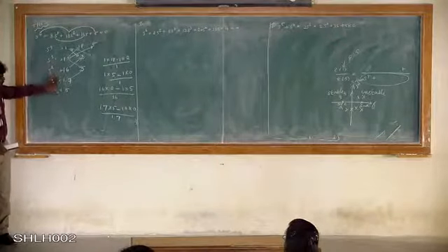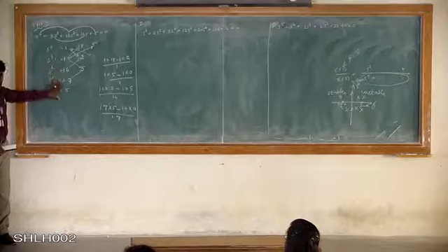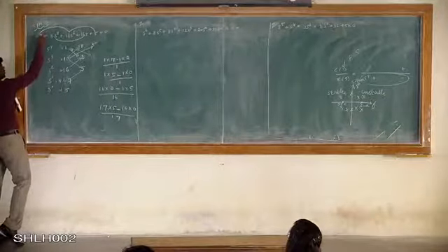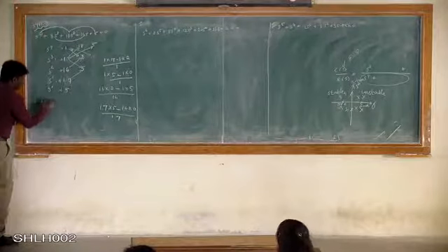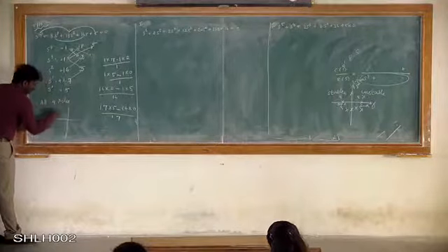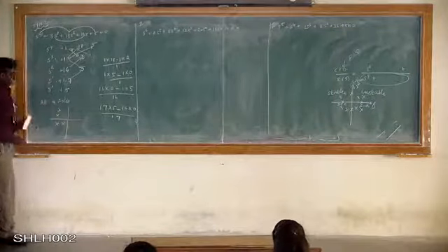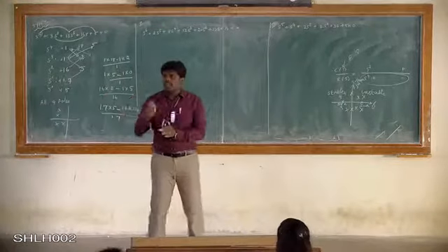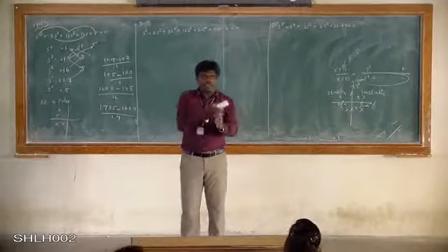Now all these values are positive, so that means it is a fourth order system. All the 4 poles are lying on the left half of the S-plane. Then the system is stable, right? So we don't need to say the pole location or where it is exactly lying.